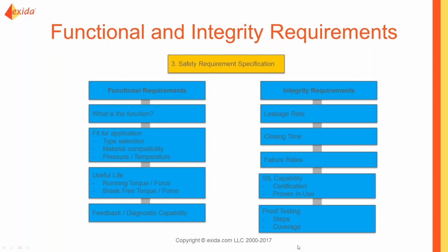So those are functional requirements, and then there are going to be integrity requirements such as what leakage rate is tolerable, what's the closing time for the valve, what failure rates or what's the target PFD average, what SIL level is the safety instrumented function, and are you going to accomplish that through using certified devices or using a proven in use approach, and what type of proof testing do you anticipate? That's another key thing that ties in with the diagnostics.